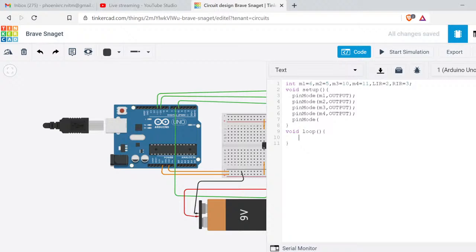So first thing, we initialize that one, but what is the IR sensor actually doing? They are giving input. Both are inputs. So pinMode RIR, comma, INPUT. Okay, everything is fine. And to begin the serial connection, Serial.begin, it is all the data transmission, the serial transmission. The data will be transferred at 9600 baud. This signifies beginning the serial communication at 9600.